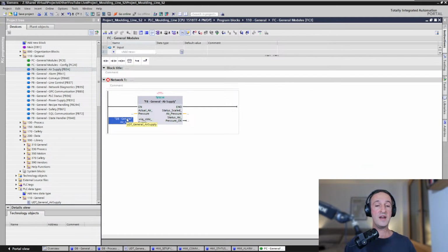That's another advantage. In your HMI, you don't need to put a separate tag for each of these individual tags. You just add the complete structure as one thing in the HMI. So parameters and buttons from the HMI come straight into the block. It's like a gateway, so the block reads and writes to the structure.